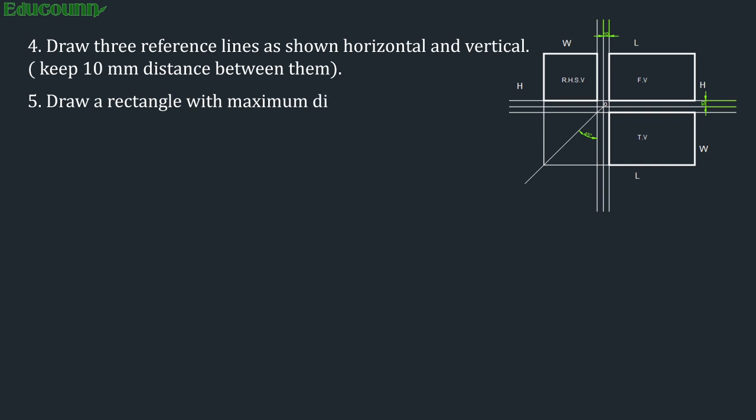So after this, we have already measured the maximum dimensions, that is length, width and height of the object. Now draw the rectangles in each view, in the portion shown there, which is divided by the 3 vertical and horizontal lines. If you have identified that RHS view is to be drawn, then it should be in the left section.